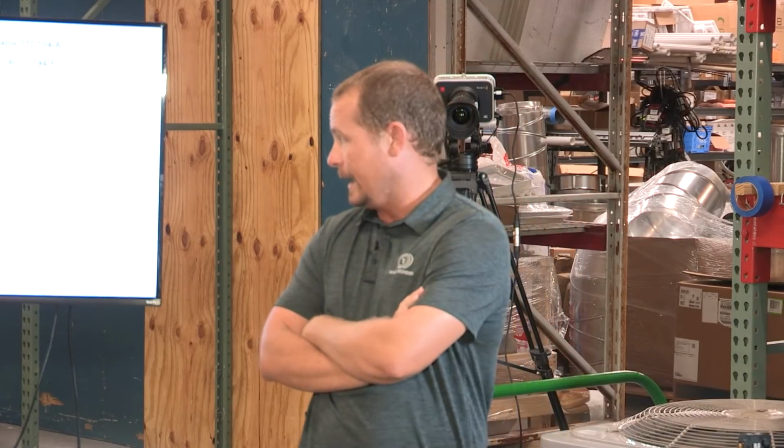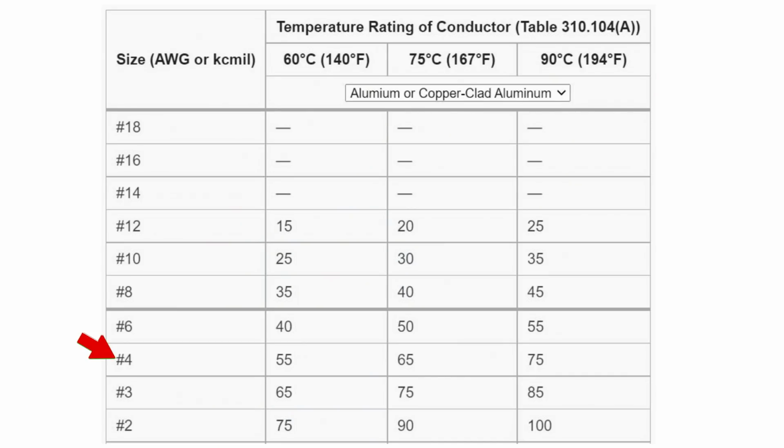So it doesn't matter what happens if that wire is properly terminated, properly connected, nothing loose or weird, and it's a number 4 wire, and it's got a 55 amp breaker protecting it. If you try to put more than 55 amps on it, what's going to happen? It's going to trip, right? So you can have a sub-panel, because this will come up a lot of times.